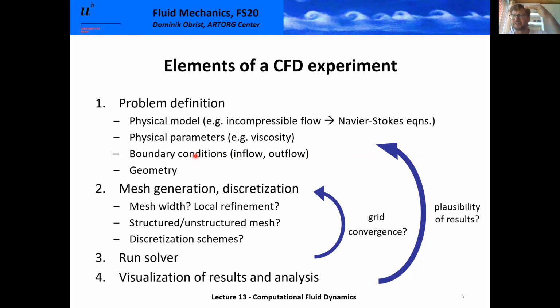But what boundary conditions do you set at the inflow and at the outflow? At the inflow, you probably need to set some velocity profile, which describes what the flow looks like as it comes from the heart. How do you know that? How do you know what the velocity profile is in the first place? Because that's actually what you would like to solve. The same goes for the outflow. The outflow definitely will be affected by what's happening in the brain.